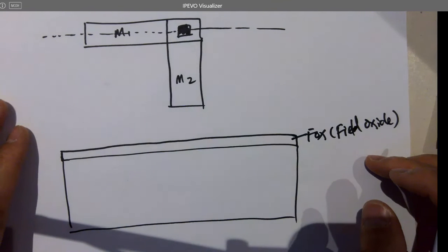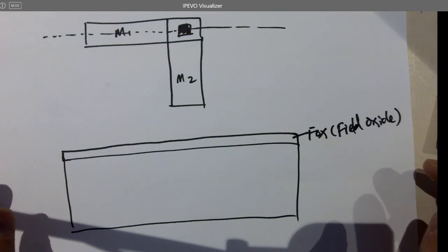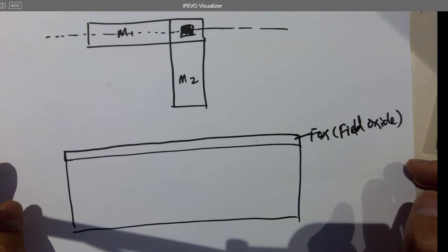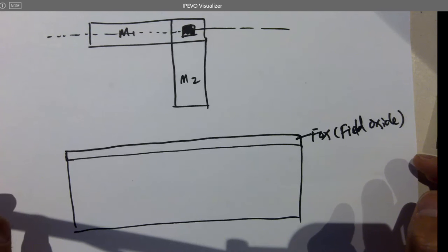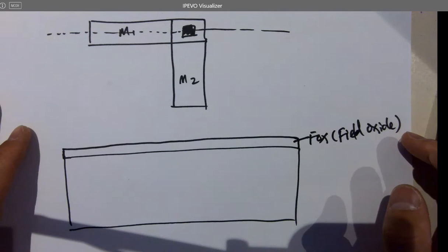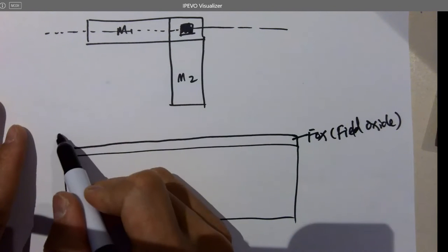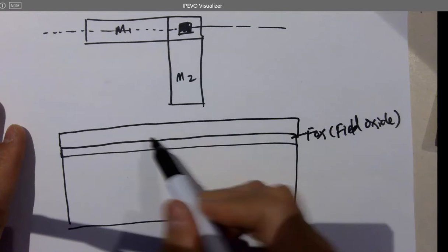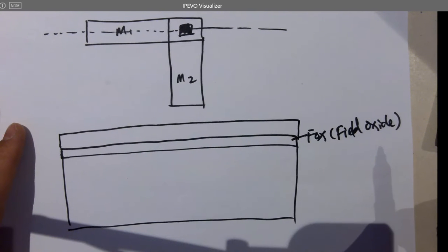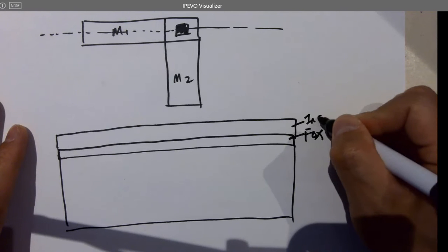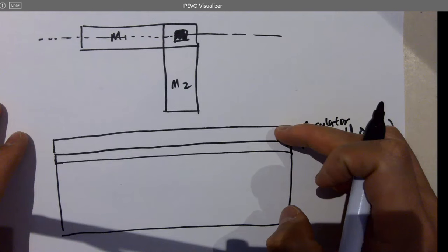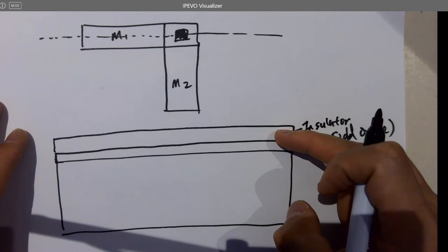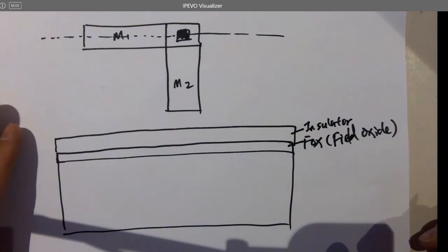Poly 1, poly 2. So C5 has 2 poly layers, just keep in mind. Sometimes you ask why we need a poly 2, since poly 1 is used for gates. I'm going to cover that pretty soon. But you do need that insulation layer here to host these 2 poly layers. Do you have anything to be drawn in insulator 1 in this layout? No.